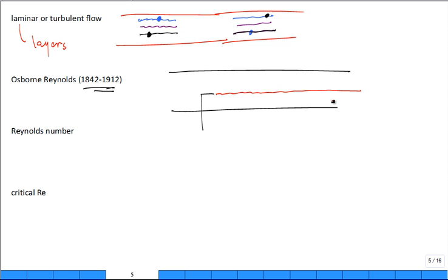And if it stayed right there, it was laminar flow. But if he turned the flow up in speed, the speed was going faster in the pipe, then that would start to mix up. And he said, okay, now I have turbulent flow. So they honor him still with coining the term Reynolds number, which is the ratio of inertial to what? To the viscous. Inertial to viscous.